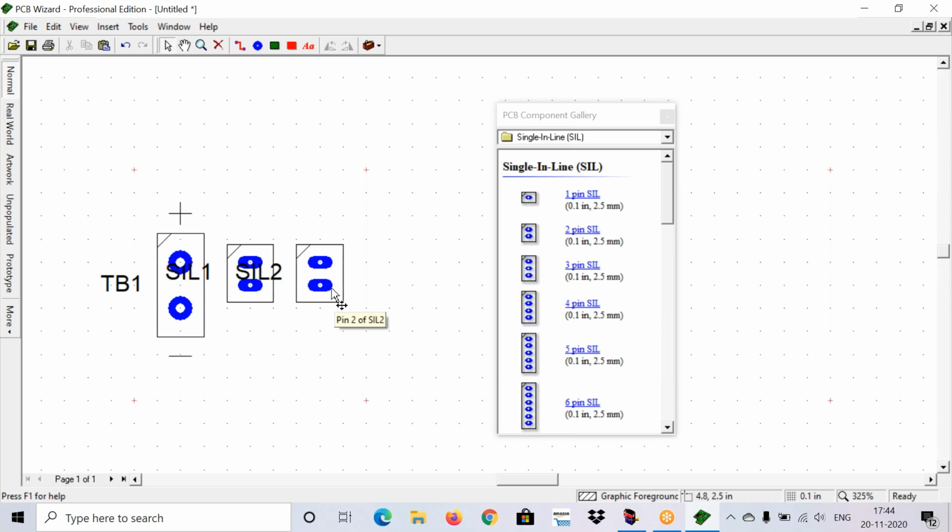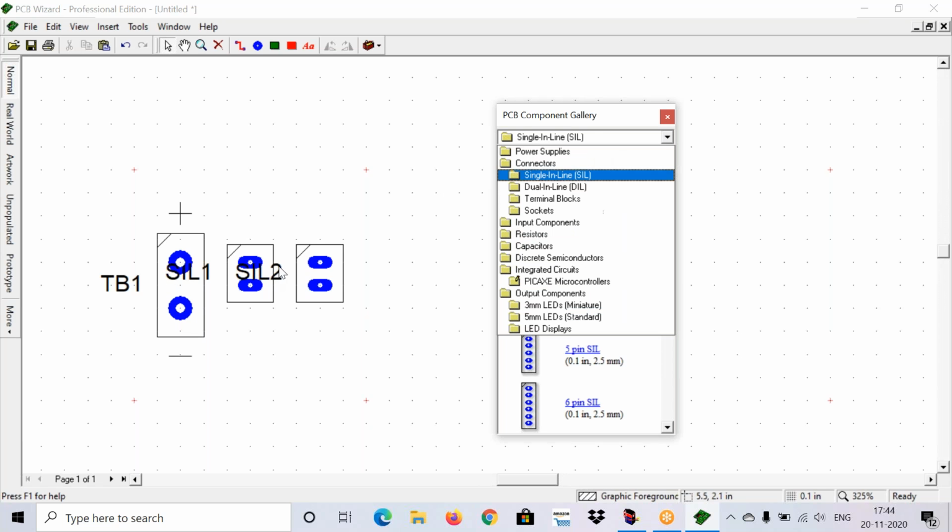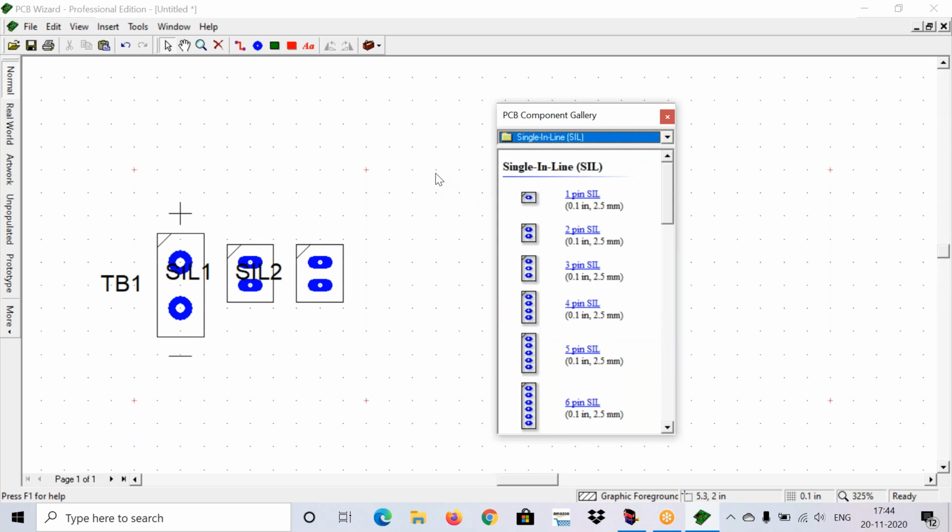These are two 2-pin connectors which are used as primary and secondary windings of your transformer. And for the regulator also there will not be any footprint. For that take a 3-pin connector. In the 5V charger circuit you need to use connectors for the transformer as well as the regulator. There will not be any special footprints for those 2 components.